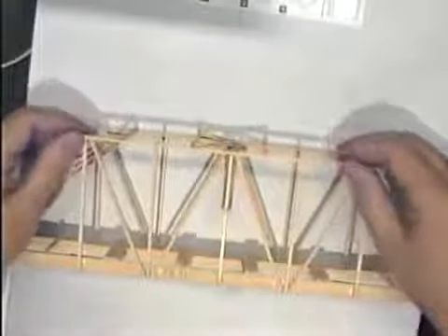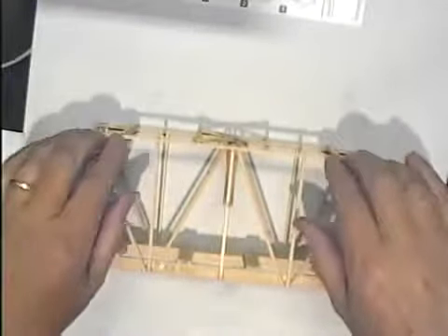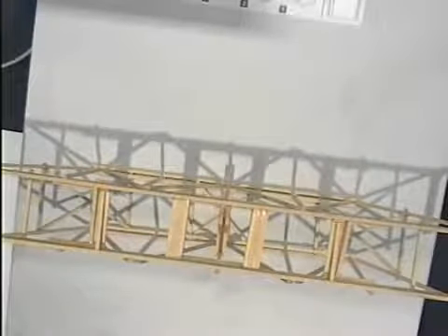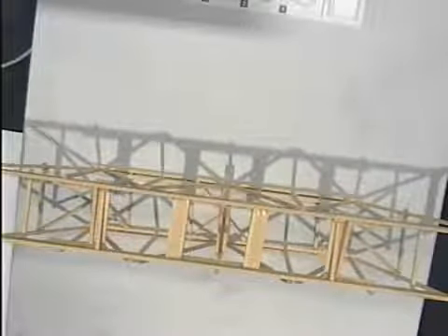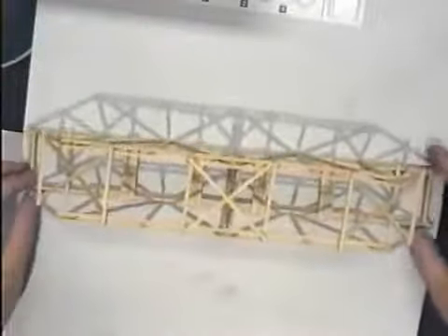Again, which parts of this bridge are going to be under compression? Which parts are going to be squeezed together? The top part. So that's where you want to have most of the cross bracing. Notice on the bottom there's very little cross bracing because these pieces are under extension or tension. Okay? So you don't need cross bracing there. You need a little bit on the top to keep those from coming together. You need something to keep the bridge from swaying. And that's why we have the end pieces here.